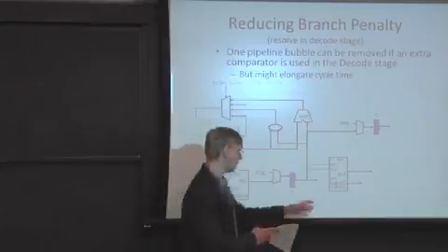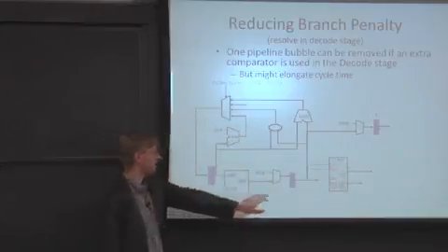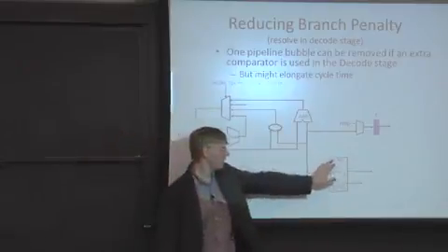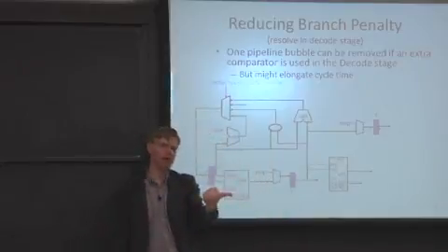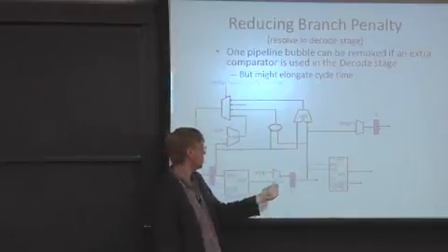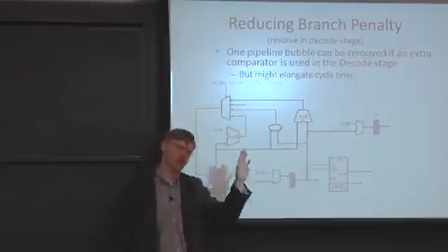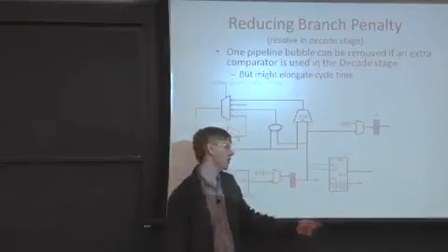So how do we do that? Well, here we have our register file. This is in the decode stage of the pipe. This is the fetch stage. What do we really need to do for a branch? Well, we need to know that it's a branch, so we do some decode. And we need to know whether it's a branch 0 or branch not 0, for instance, if those are the only 2 branches in our architecture.